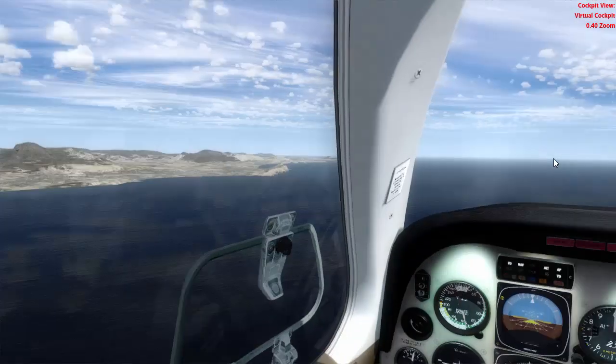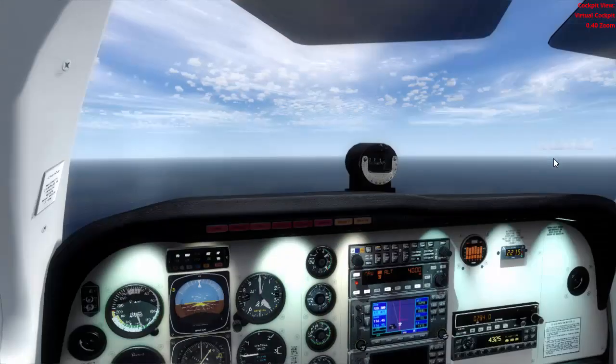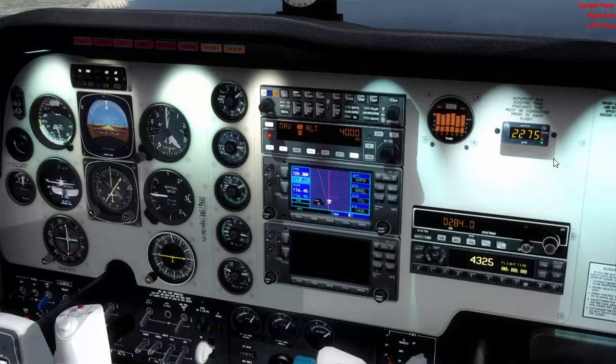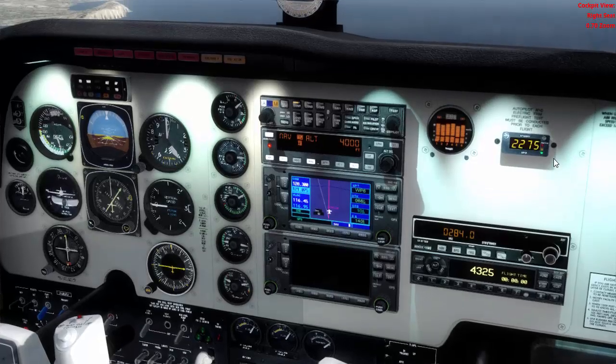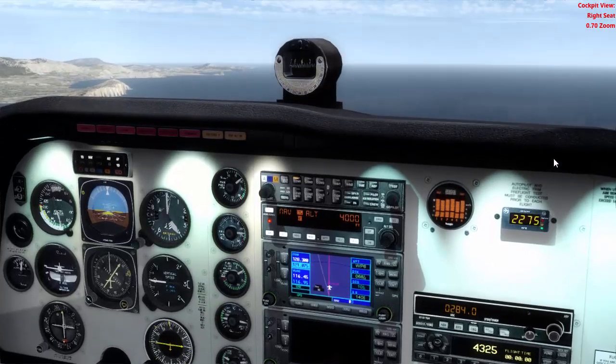Don't worry, if you get confused and took the chart for the value of 23, okay, you won't die, okay. It's an error, it's not good, but you won't die, don't worry. It's not a fatal setting, okay? Something fatal is if you do not heat the pitot tube.